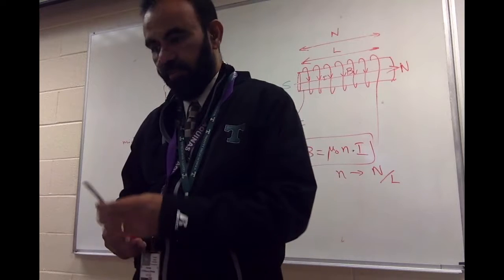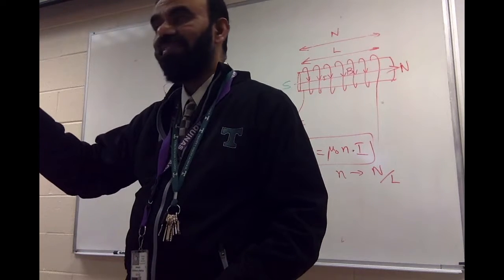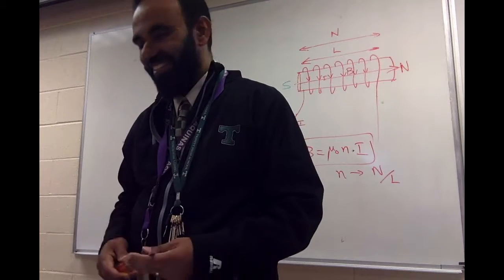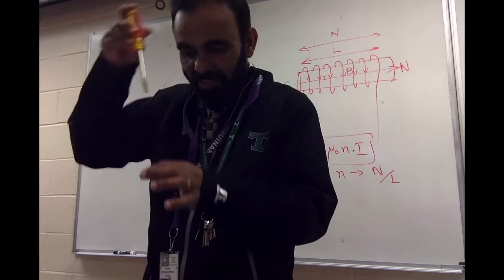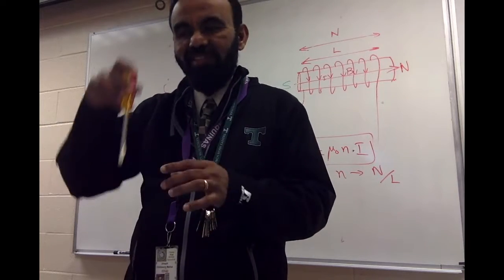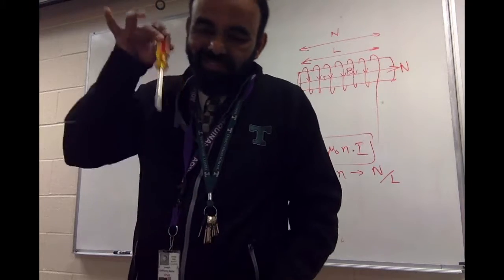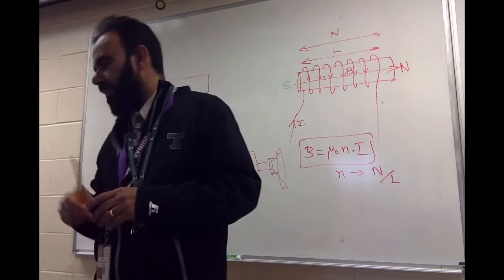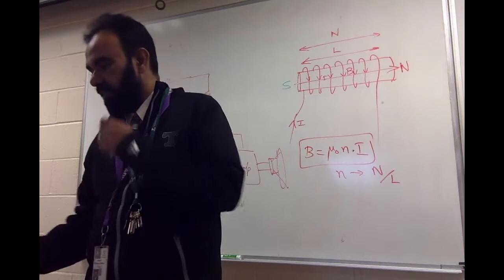All right. Oh, it's magnetized already. See, because you put it inside for some time, it's already magnetized. So yeah, it is very useful actually, because when you are trying to put in a screw somewhere deep, this will be very useful, just to get it magnetized. Or if the screw falls off and it is pretty difficult to reach it, this is the best way to go and pick it up. So that's why most screwdrivers actually have a steel tip which can be magnetized.